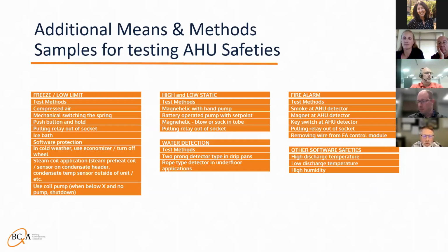That's why you need to bring your local setting above that activation set point. Going up to the max of the device, which is 2000 ppm, will definitely set it off. And that's why you've seen the 1999 in that screenshot. What we couldn't do at the same time was video in one room and in the other room at the same time to be able to see as the device dropped back out of that 1999 and was dropping down and then going back up and settling out.